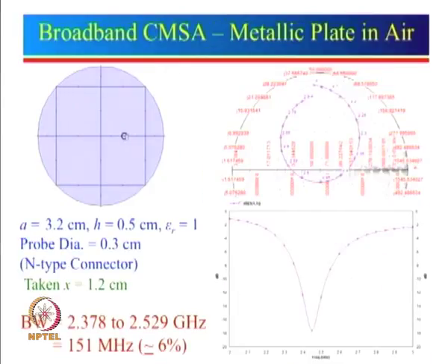Then the results will come and you can calculate accordingly. In fact, if you add a little bit of thickness here, effective a will increase, which will reduce the resonance frequency. As I mentioned, I had taken a larger margin on the higher side, so that will do the job. So if you use this particular dimension with the proper support, it will easily cover the Wi-Fi.